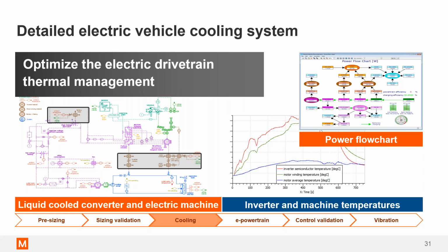And in fact, the latest version of AimSim, which was released just a couple weeks ago, takes this one level further and really breaks down the thermal behavior of the motor. So being able to tie in detail the motor performance at different temperatures as different components change temperature in the motor, along with your cooling system, and tie that all really well together so that you get an even more accurate representation of how your machine is going to behave over different duty cycles, different cooling conditions, different ambient conditions.